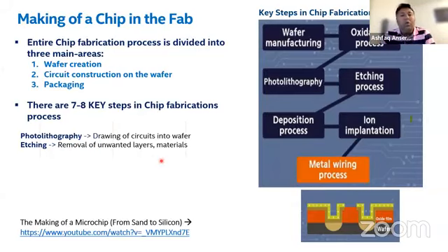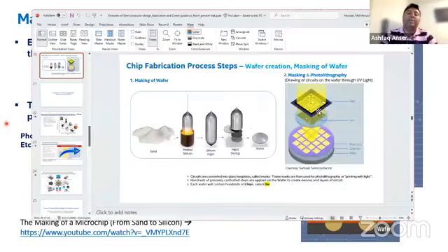Now you have the surface, and you need cheese and sauce to make the pizza delicious. Cheese and sauce for us is the photoresist chemical. So we add photoresist chemical to this wafer and expose it to light. We also put the design blueprint that Brother Manzoor and his team have made on the wafer surface, and with this photoresist material, we imprint that circuit design on the wafer surface. Because it's photo, we call this step photolithography.